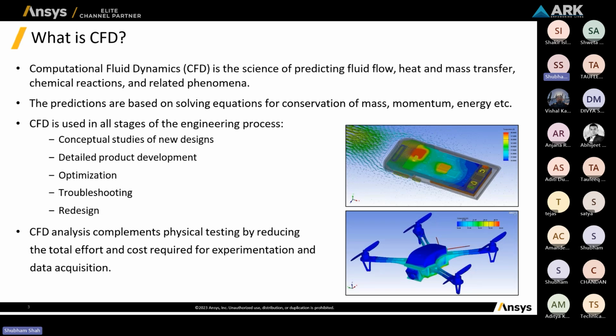So when you go with the CAE results or CAE simulations, you will come to know and identify the location. Now you can go back and change your CFM, either increase or decrease it. Let's say you have increased your CFM. Now you can see that your hotspot region is slowly disappearing. So this is one of the ways CAE can be used.